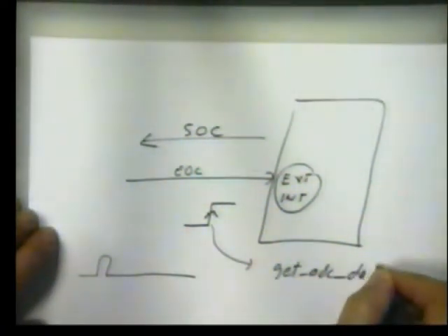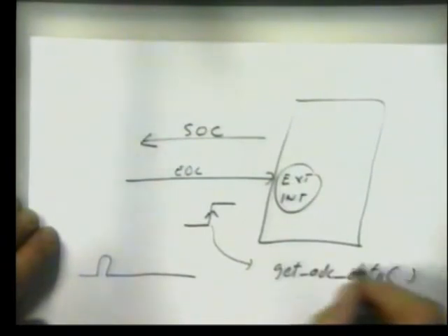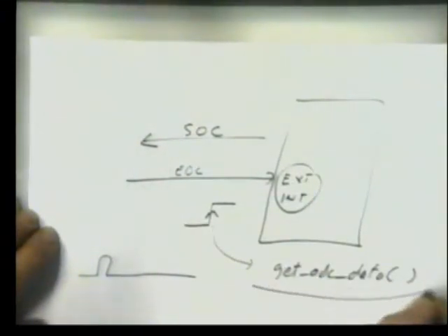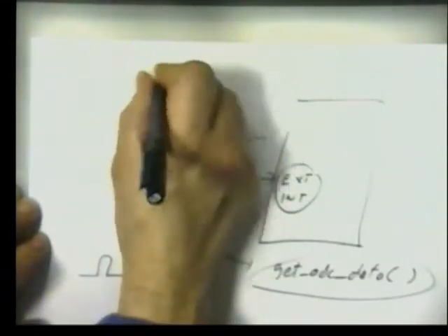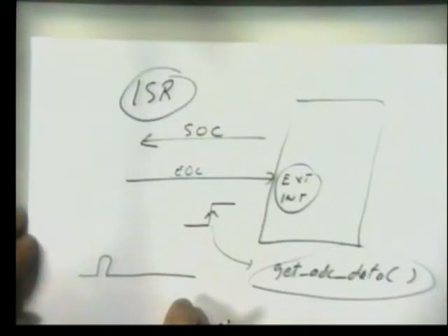ADC data. The difference is that that get function, instead of being part of our process, is now an ISR, an interrupt service routine. It's a parallel process. It's totally independent of our main body of our program. Now, I'm going to put these to one side. I'll return to them later because there's some important analysis we've got to discuss about this structure in terms of data handling.